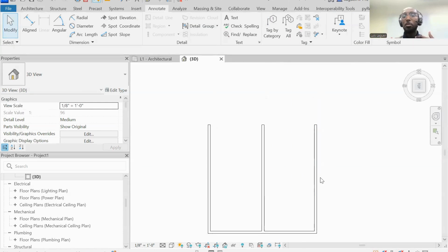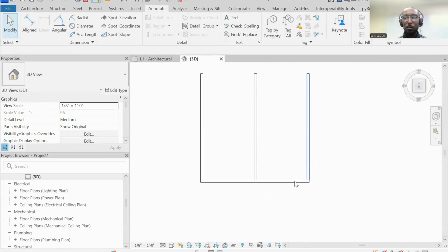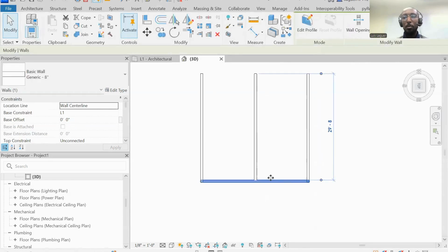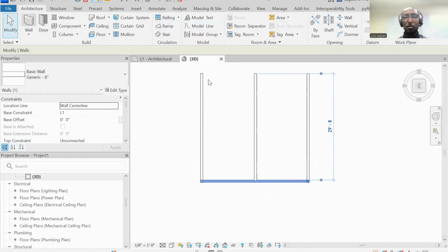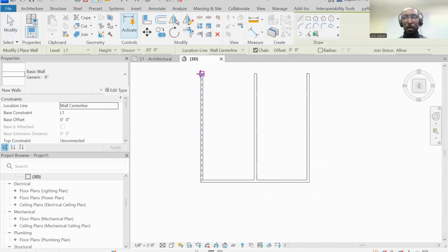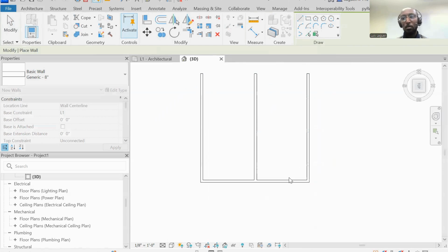There are multiple ways, a lot of times, to use things in Revit and to make things happen in Revit, right? So you see I got these walls over here. Let's say I want this wall to also line up on the other side, right? So I want to enclose the space. Now obviously, I of course can click the wall. I can use my selection box from here and go all the way across. We could do that, or we could do something else.